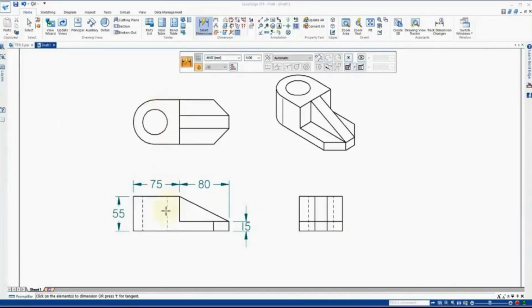Now the dashed lines, when you're looking at this from the front view, what are these dashed lines? If you run this straight up, you'll see it's the circle. And so in the front view, you can't see that circle, and so that's why you have these dashed lines. When you go up to the top view, yes, you can see the hole for the circle, but you can't see that in this view right here. That's why they're dashed lines. Same with this view over on the right. If you look at this, those two dashed lines are the circles looking down this way.